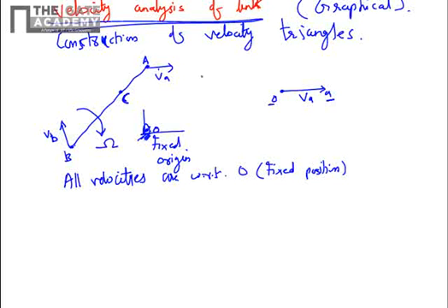This is the fixed point, VA. The magnitude of the vector is the same as the magnitude of velocity VA, and the direction is also the same. Now we can also determine this likewise for point B. We know VB. So let's say this is a vector VB. This point we will term as small b. All velocities will be termed in small letters, and actual links in big capital letters.